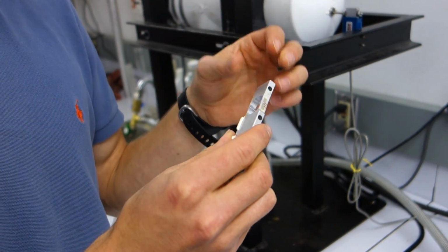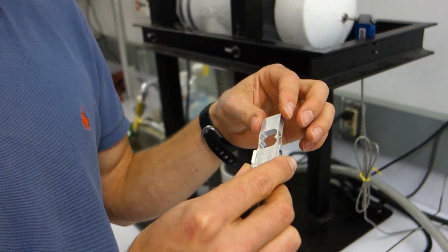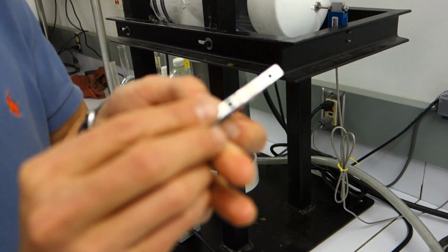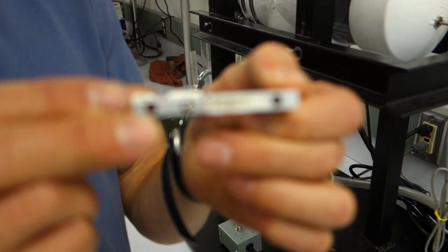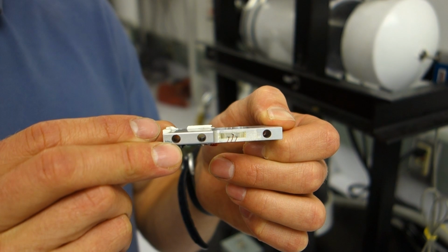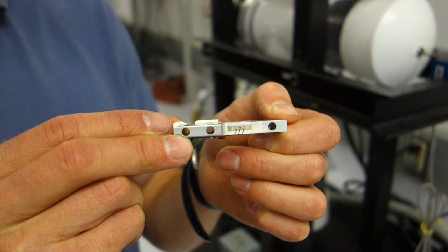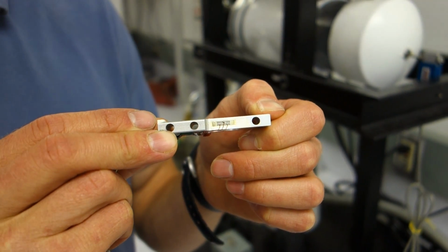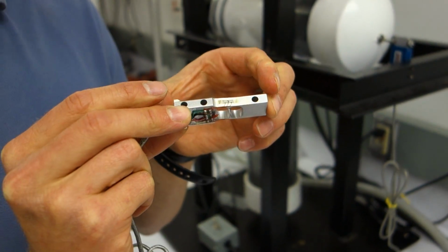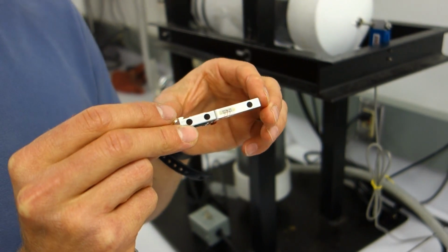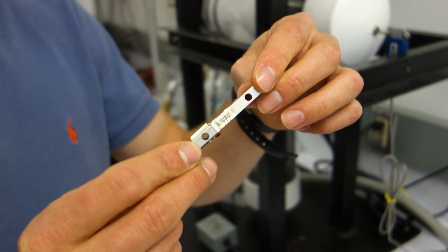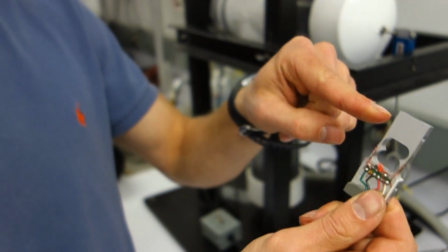So we're going to be changing the resistivity of wire via elongating the wires. And how we're going to elongate the wires is, as you can see, very small, you might not be able to see it in the video, a fine mesh of wires running back and forth. So there's a lot of wires in series, and so a small cross-sectional area change of every wire, summed up over all of them, will create a noticeable change in resistance. And so we're going to change that cross-sectional area by pushing on this flexure element here.